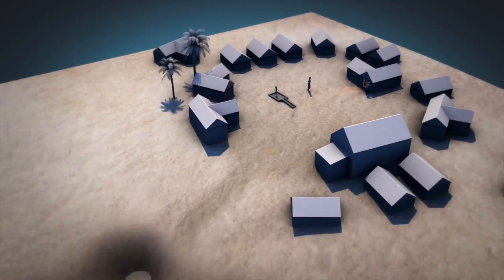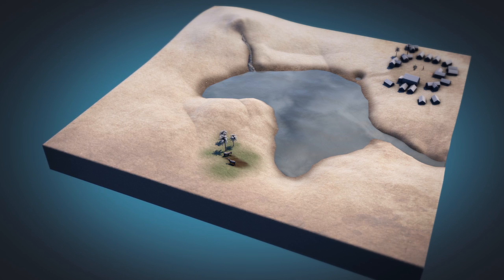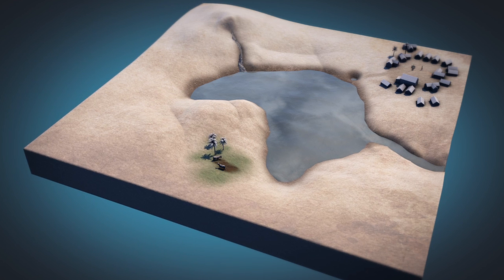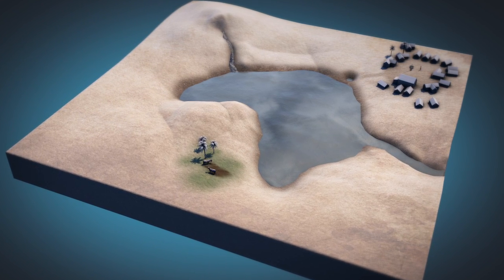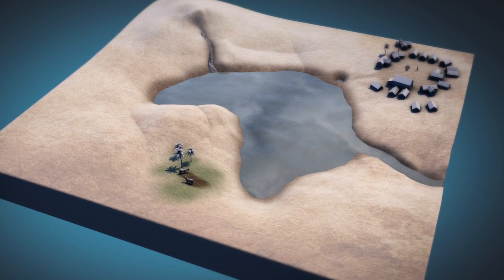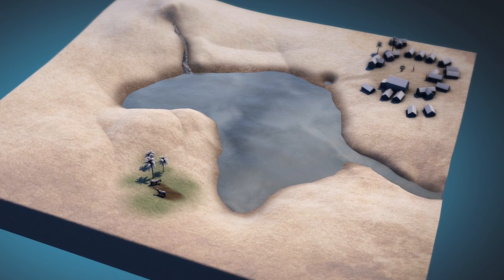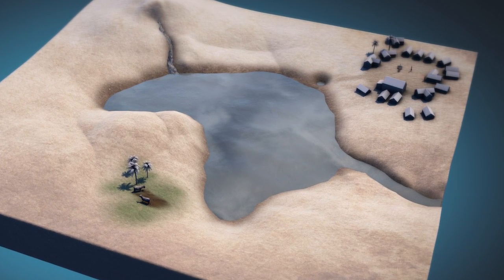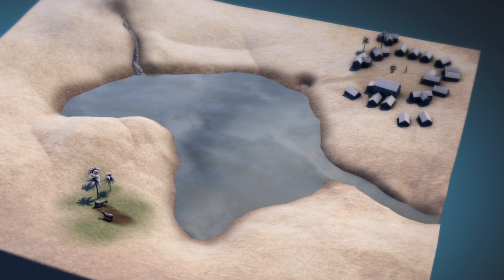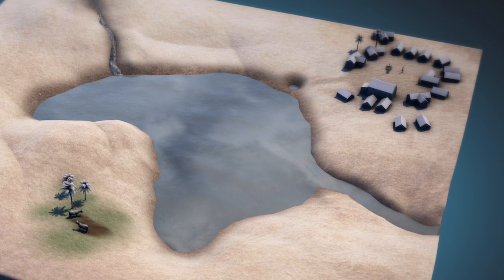So there are many opportunities for contamination between the original source of drinking water and the actual point of consumption. A big advantage of household water treatment is that it offers the possibility of removing any contamination that is introduced at the water resource, the delivery system, or through collection and transport. Many household water treatments don't prevent recontamination, so it is important to have safe storage after a treatment step. And likewise, good hygiene, especially washing hands with soap, is important to minimize the possibility of clean drinking water becoming contaminated just before consumption by using a cup or glass that is fecally contaminated.